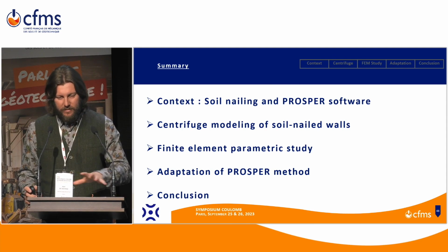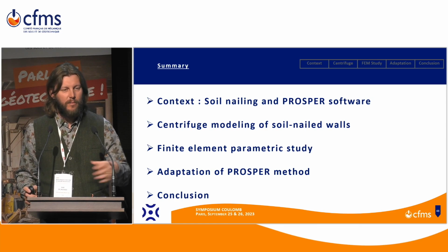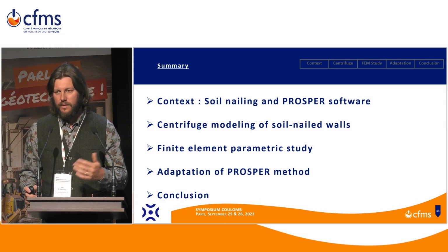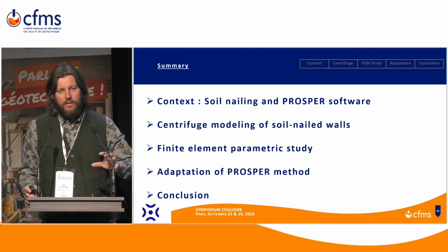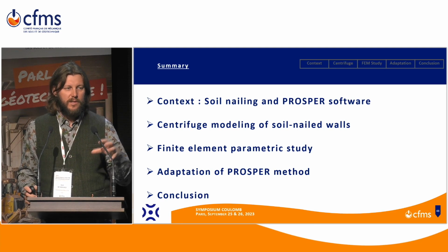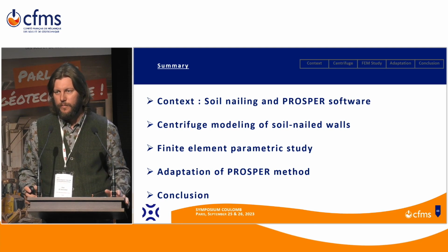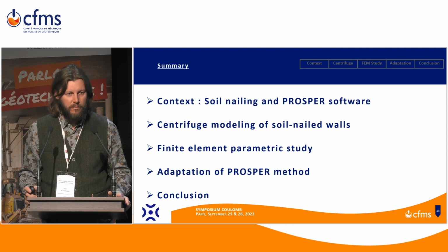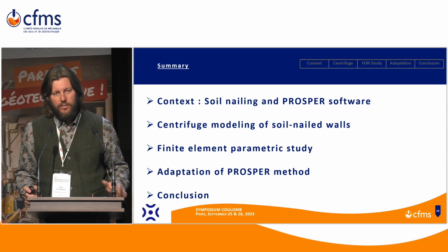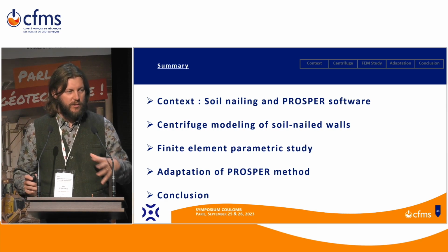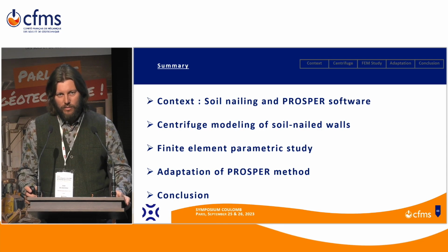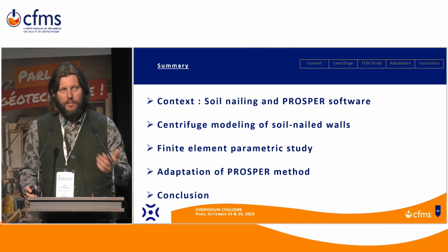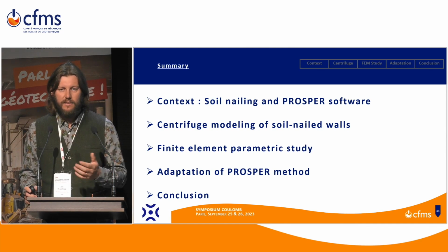And then I will try to describe the method we used to better understand the mobilization of nails in a soil nail wall. This work included the experimental part, which was done in centrifuge in Nantes, on the Nantes campus of Université UCFL, and a finite element parametric study. And in the end, combining all these results, we tried to propose an adaptation to the Prosper software, which aimed at a better design of facing of soil nail walls.